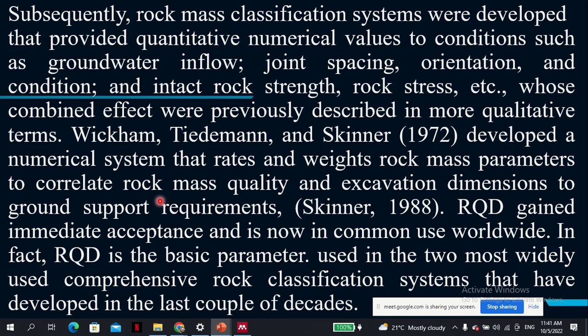However, RQD is useful even now and is based on the fact that when you're drilling, you recover cores that have lengths more than 4 inches, 10 centimeters. So if you can recover rock that stands continuously for 10 centimeters, then this is a reasonably good rock.